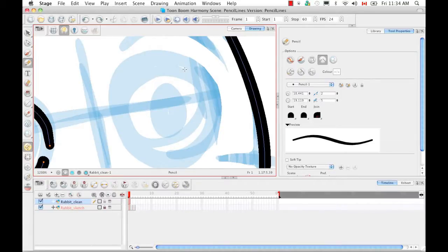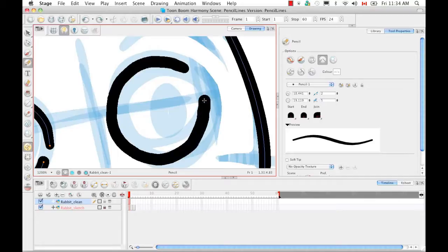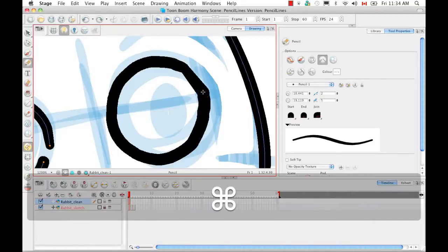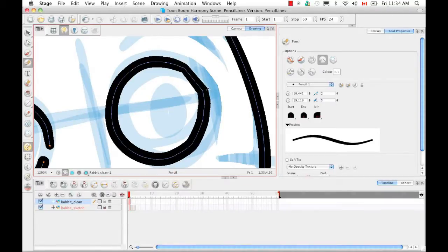So I forgot to mention that it's actually Alt on Windows or Linux, but that it's Command on Mac. So as I'm drawing my circle, I'm coming around to the end, I'm about here, and I hold down the Command key and I release, you can see that even without bringing my pencil to connect with the other end, the pencil line just shot forward and connected automatically.